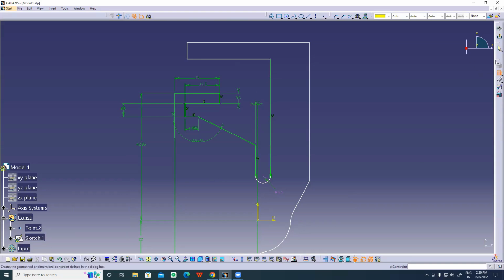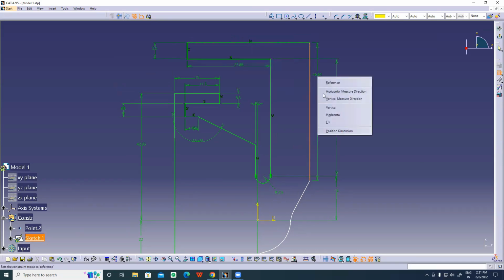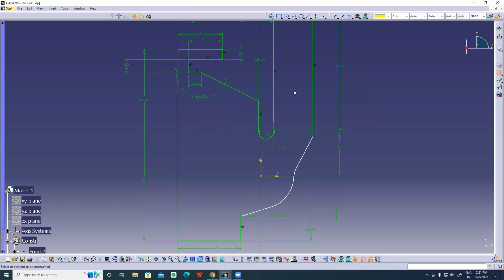Then what we can do is again double clicking on it, and I wanted to set exactly where the circle part should be, or else the starting point should be. I'll be applying like this, and I'll be selecting the line, applying a dimension. Now select this, right click, horizontal relation, and selecting the line, apply a value. Right click, vertical relation, select this and apply it. Select this line, horizontal, and select this line, right click, vertical, and select this line, apply a dimension from the vertical axis.